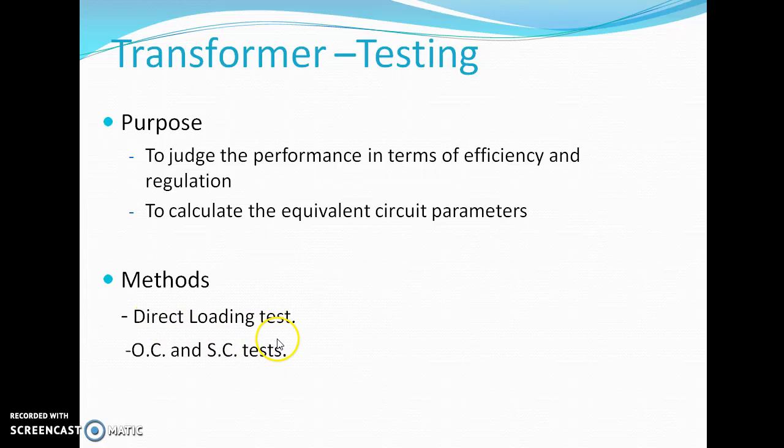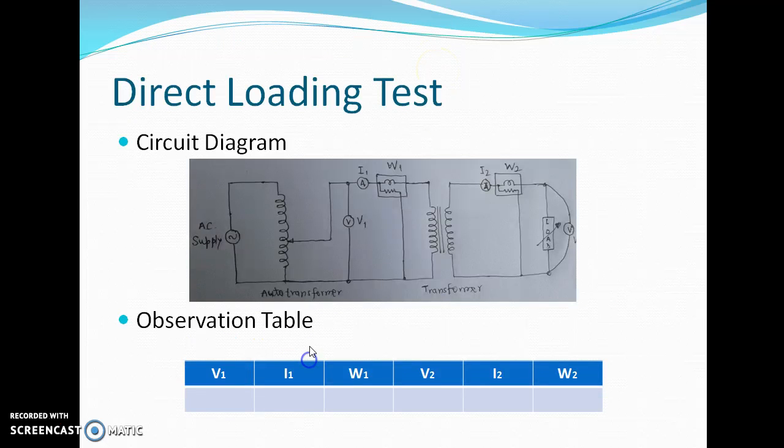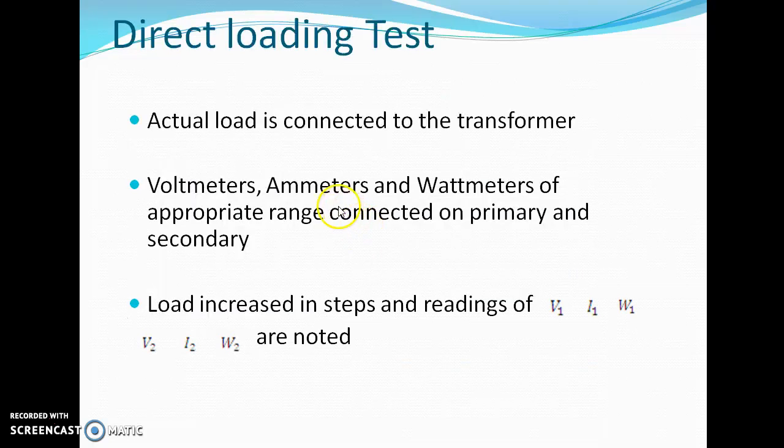So what are the methods for testing the transformer? Generally two methods are used. First is the direct loading test, and the other is by performing open circuit and short circuit tests on the transformer. Let's see the direct loading test.